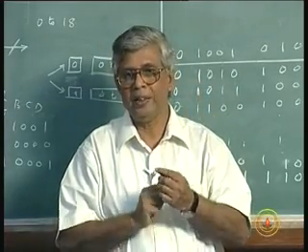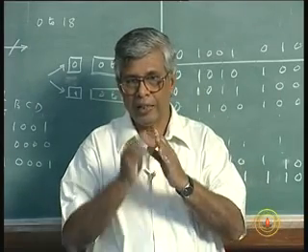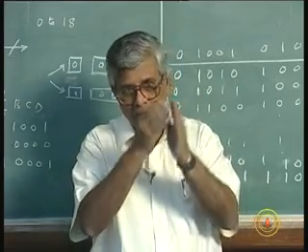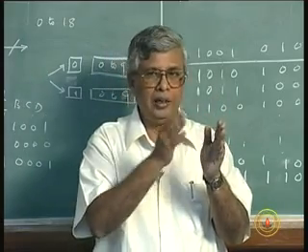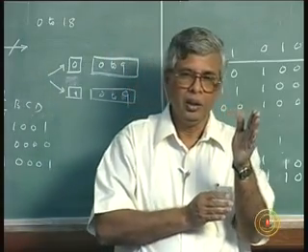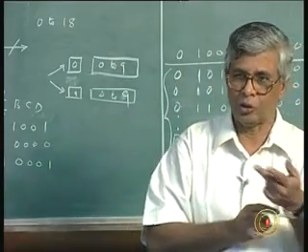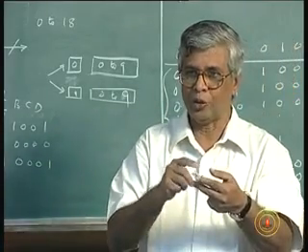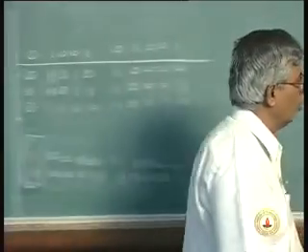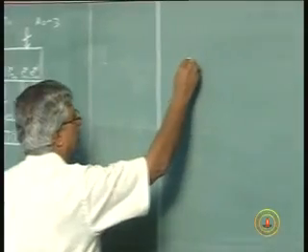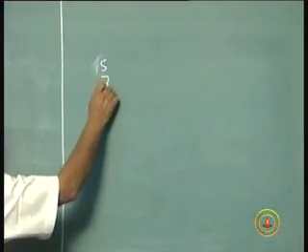That means I need to add 6 to that. It becomes 18. Out of that 18, that 1 will come separately. 16, that last one is the 16. If you remove that 16, the remaining is 2. The 2 will be converted and shown on the 7-segment display. So 5 and 7 give 12, no problem.